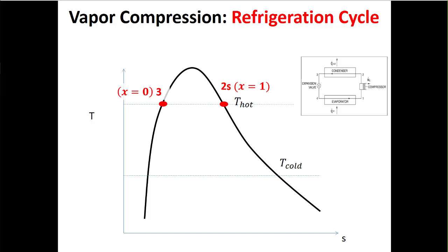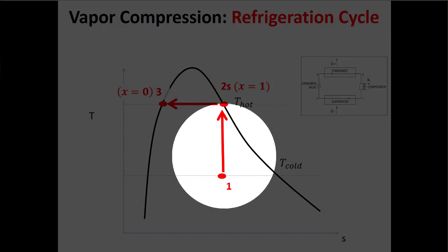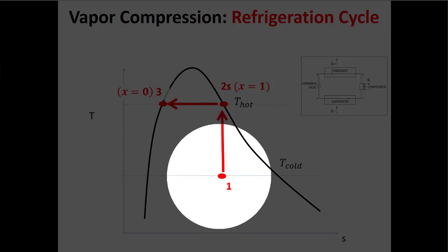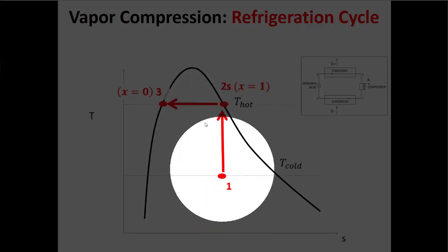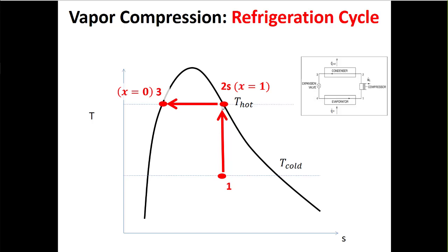So this also happened in the Rankine cycle, right? But we were doing it on the bottom half of our curve, right? Because everything's kind of inverted in this TS diagram, right? So this is our condensation process. Now, if we had an ideal compressor, then in order to get from our low pressure here in the evaporator up to our high pressure here in the condenser, we vertically move up from state 1 to state 2S, if this compressor was ideal.